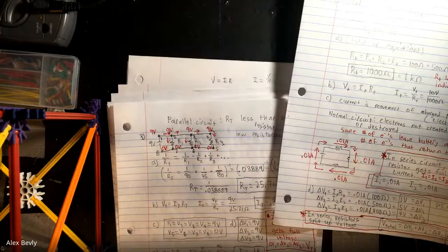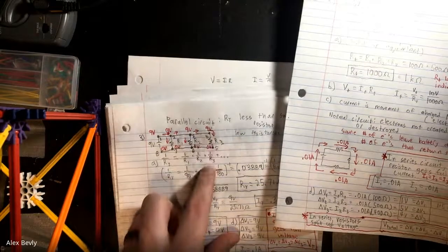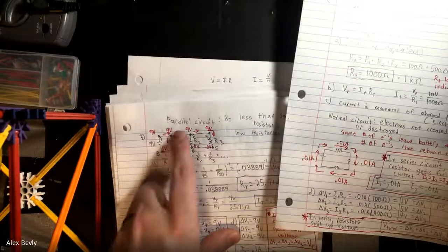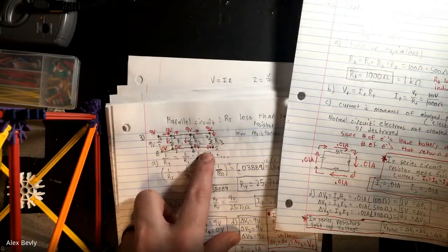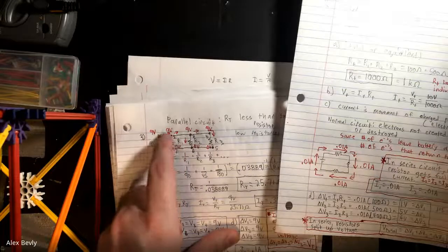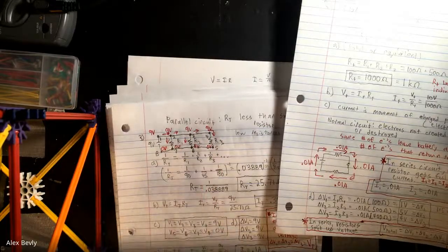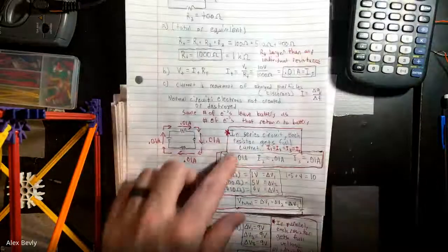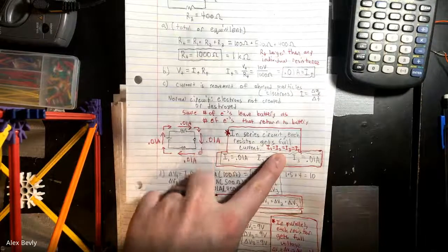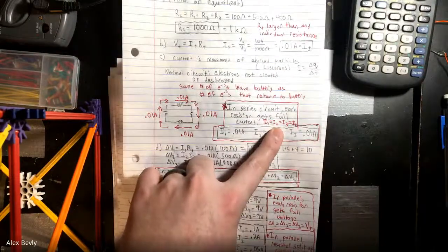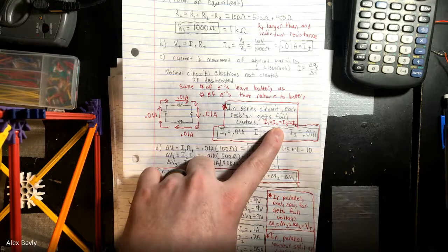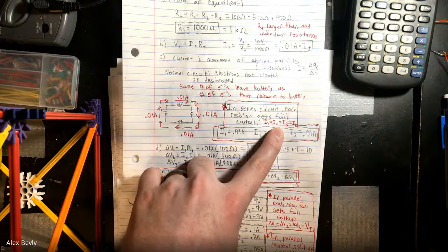So electrons, they're a single electron. They can only go through one path, ignoring quantum mechanics. They can only go through one path. So they have to choose. Some electrons go through 1, some electrons go through 2, some electrons go through 3. So the current itself splits up. They make a choice. So series, all the current goes through every resistor. Each resistor gets the entire current, the total current. But in parallel, the paths split, so the current splits up. So the sum of the currents equal my total. So they have to share all of those currents.